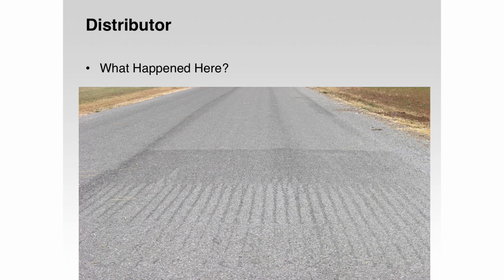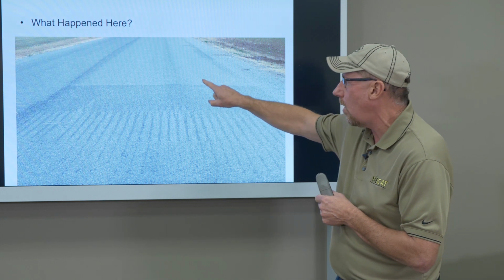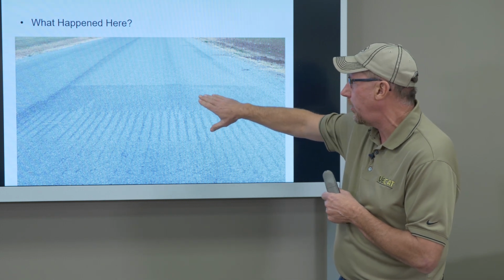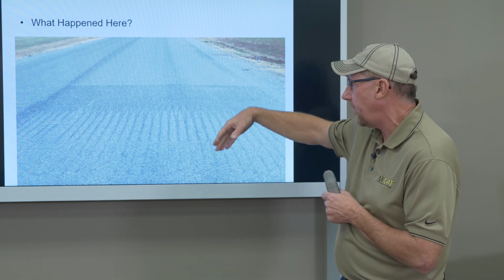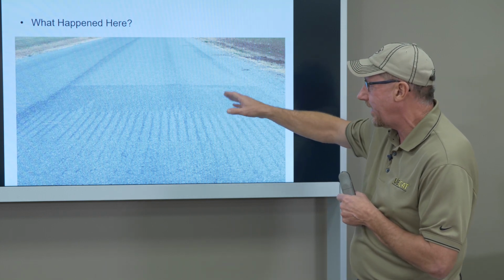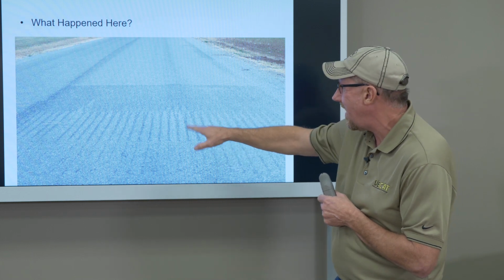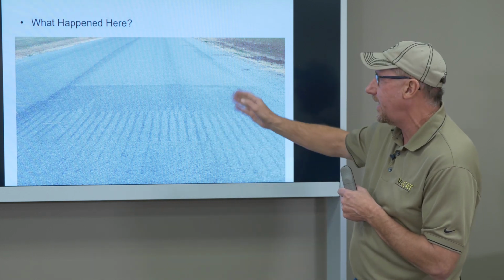Okay, everybody's seen this, I'm sure. A guy takes off, he gets a puddle, and then it dribbles, and then it sprays okay. We've all seen that on job sites, and this is what we call operator error. There are ways to make this go away, because this always happens at a butt joint on a paving job, and now you got too much tack right at the butt joint, and people are all mad at you because they got to try to rake some of that tack away. Then I don't have enough in here, so you back up and you do it again.